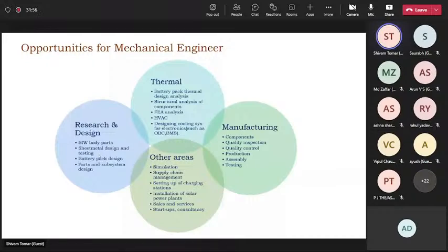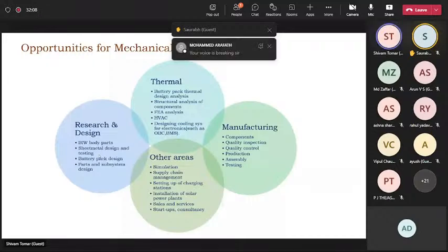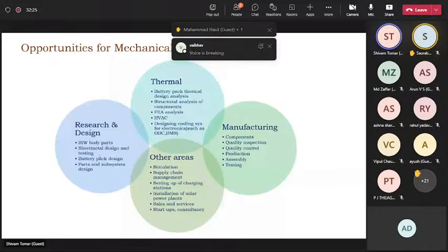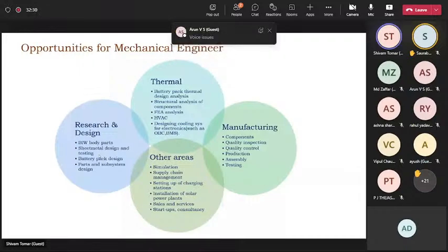We are not using any other material. If we talk about passenger cars, or light shaped vehicles, whatever components you see are designed from sheet metal. Why are we using sheet metal? Because components designed from sheet metal are lighter as compared to components designed from I-section bars or other kinds of cross-section bars.